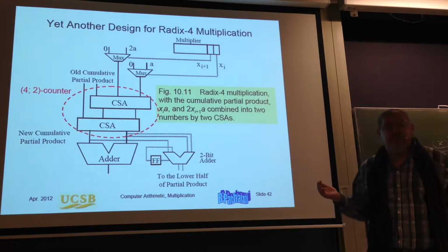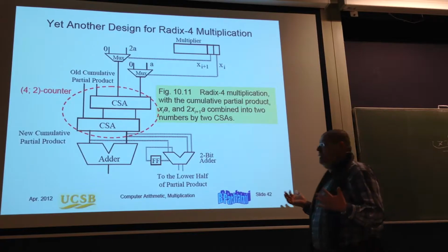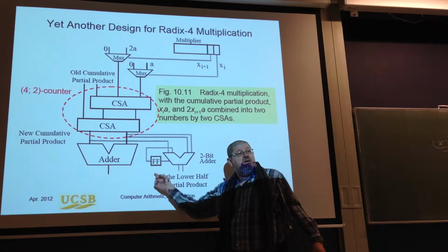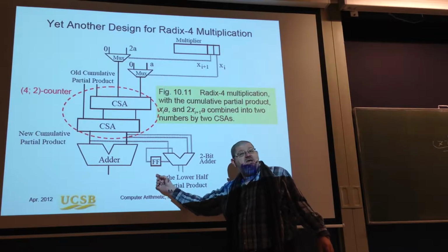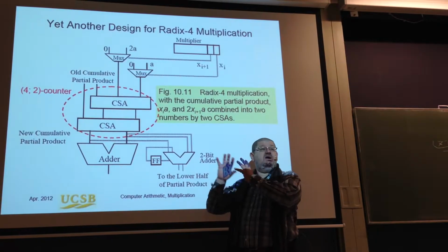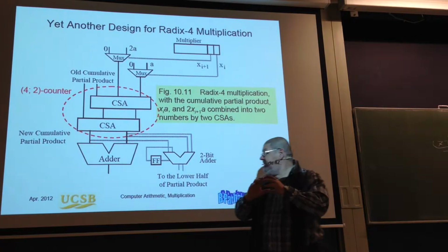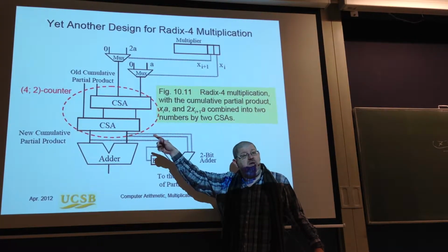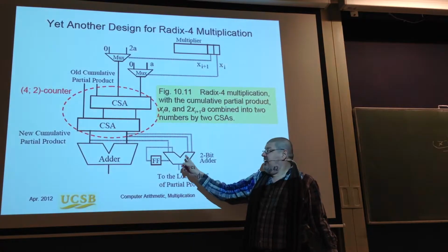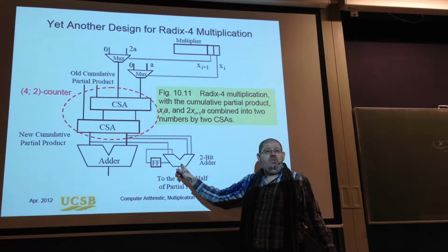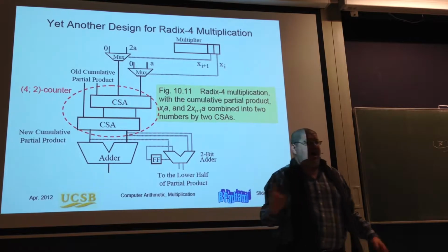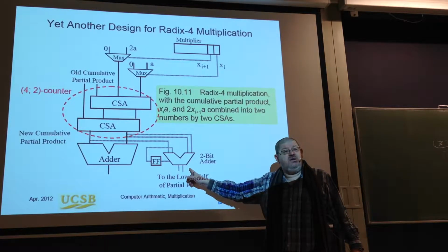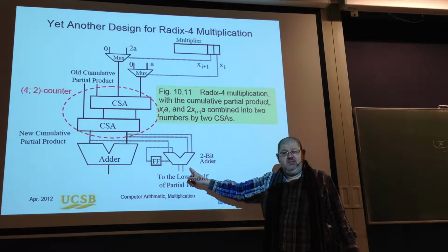When I keep the accumulated partial product as two numbers, then I have to add this adder here, which will take the bits which are going for output, will propagate the carry, and will keep a carry for the next iteration. If I consume more, I have to add more. And then eventually, I may end up with this part dominating the calculation and imposing the cycle time.